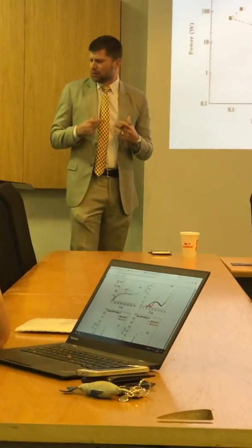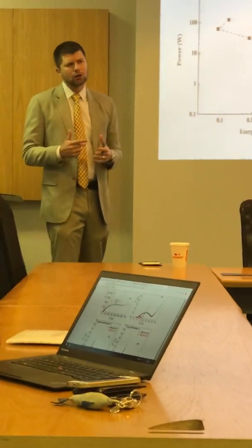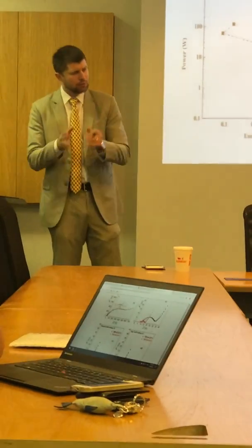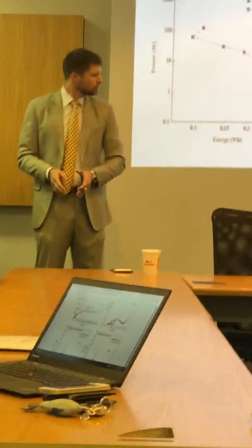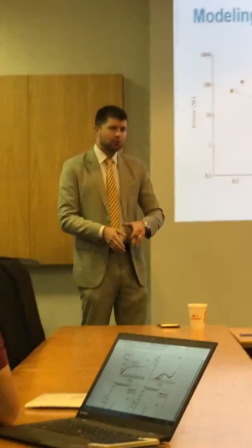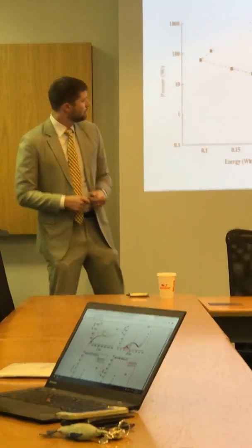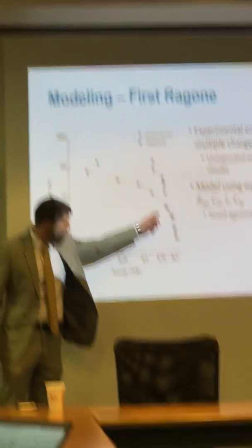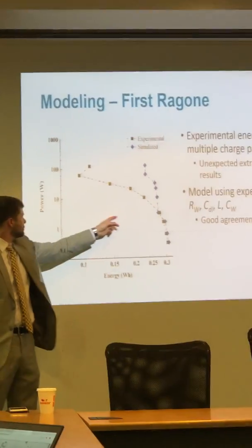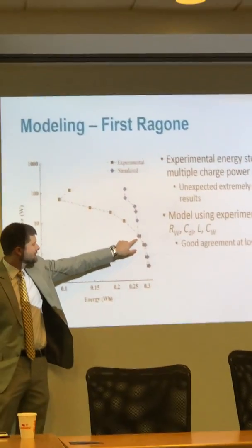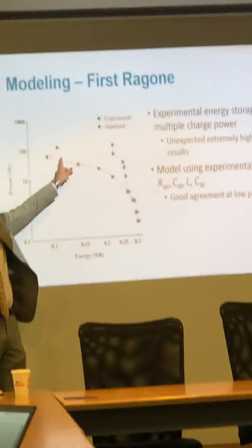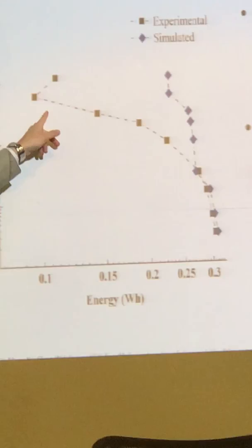And then, as I said earlier, I charged this experimental Randles circuit, and I charged real-world devices at a bunch of constant powers, and found that there's pretty good agreement at low power, but, okay, this is 3 watts here. Above 3 watts, there's some significant divergence.